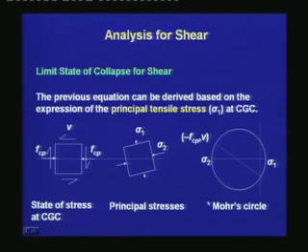If we plot these two stresses in the Mohr circle, then we find that the point describing the state of stress is given by this point, where the point corresponds to the vertical surface with a compressive stress of minus FCP and a shear stress of V, whereas the horizontal surface is given by the point lying on the vertical axis, where there is no normal stress, but there is shear stress of V. From this, we can find the expression of sigma 1, the principal tensile stress, and observe that the value of sigma 1 is much smaller than the magnitude of sigma 2. This is the case when there is a prestressing force in a section.